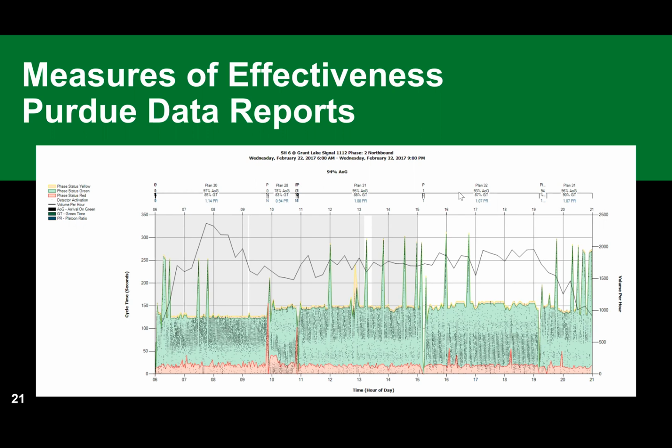Yes. So each detection zone, each lane needs to be separated out. I know you can put double loops on the same channel. The reason we need this is for lane by lane utilization. It's part of our calculation. So sometimes we'll go out to deploy, and there'll be some existing detection out there. It might need a little bit of supplemental detection. Maybe we say there needs to be some advanced, and that's a great opportunity. We talked about magnetometers earlier. We actually manufacture a magnetometer called a pod. It's wireless, and to drop something like that out there at advanced is great. But yes, sometimes we'll come in and maybe even the video is on two running on the same channel. You'll just have to upgrade the channel there to allow for two different channels coming in. So it does need to be separate.